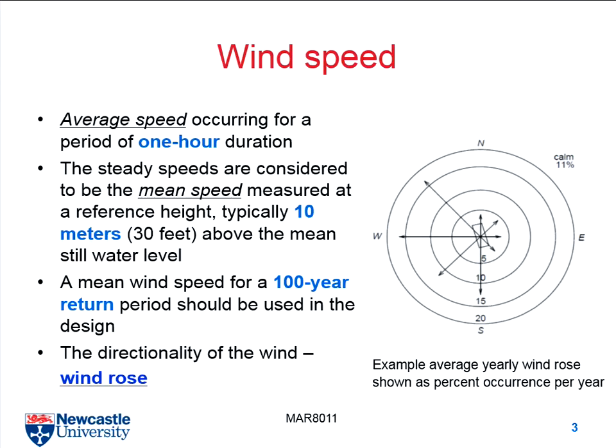So when we say wind speed, if you don't have any other requirements or instructions, we assume that the speed is at 10 meters over the ground, because in this part it's not the real case. And we have exactly the same thing over the sea. If we assume that here is the water surface, you also have friction from the water. So we assume that it's 10 meters over the water surface, or roughly 30 feet.